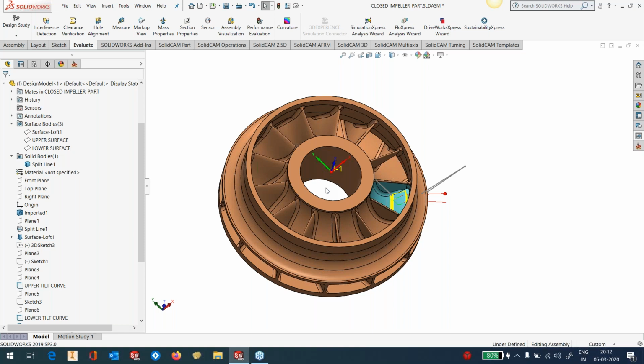Okay, so now you know how you can work with the generic 5-axis engine and how you can generate the toolpath. There are a few takeaways from this exercise that we just did. Number one, you need a very good CAD engine, and that's where SolidWorks comes in handy. You need to have the CAD engine right next to you to create construction geometries. Very important. This is actually our strength, that we have got SolidWorks right next to us. We can work with SolidWorks and create the geometries.